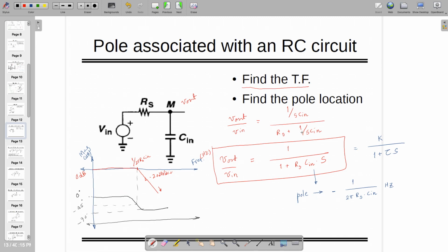In this case we can find out in another way also, that says that if there is a capacitor, the effective capacitor is going to give you one pole. So if there are two effective capacitors, it's a second order and you might have two poles. You need to find out those locations.